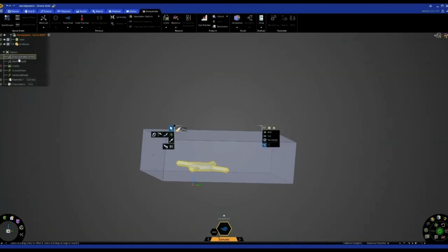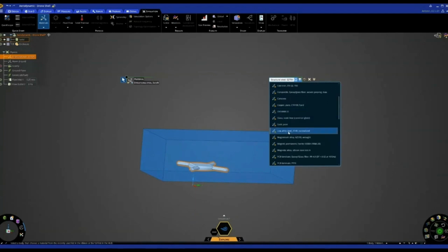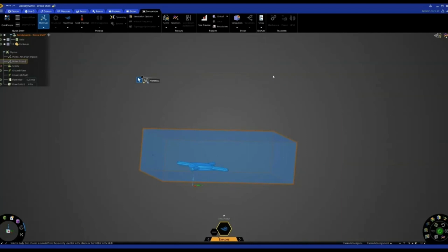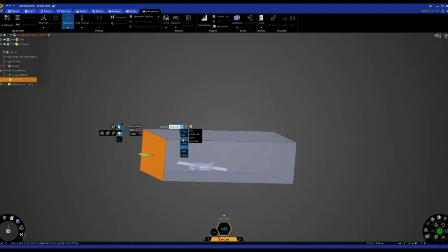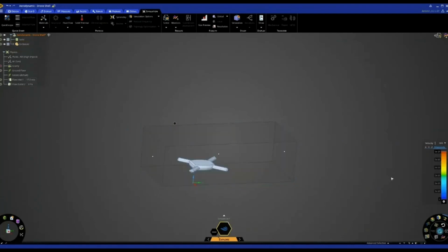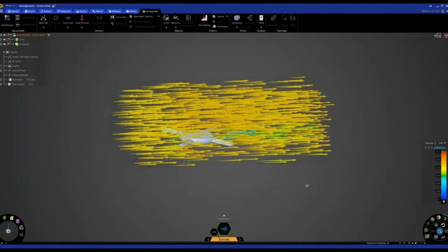And change our setup again. So let's just change that to ABS. And our water to air. Change our inlet speed lastly to 40 miles an hour, same as before. And you can always create your own fluid volume as well and do this manually without the quick start guide. But very quickly, within a few seconds, we'll start to get more results on a more aerodynamic part.